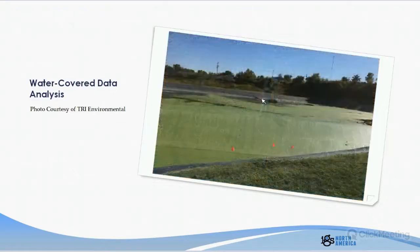So what you end up with, for example, in this survey where I got leak signals on 3 different lines, which could be attributed to 3 different leaks or one leak in the middle. And it's really hard to say where the strongest signal is unless you have some method of recording, and then you could perhaps label the flags with what voltage reading you got at each one so they can kind of guess where exactly the leak is.